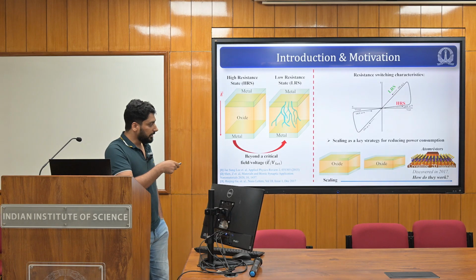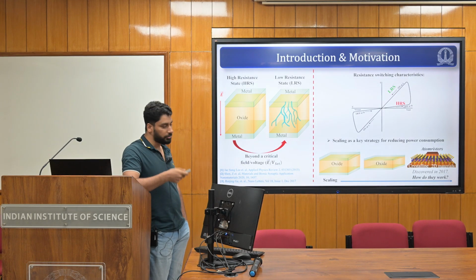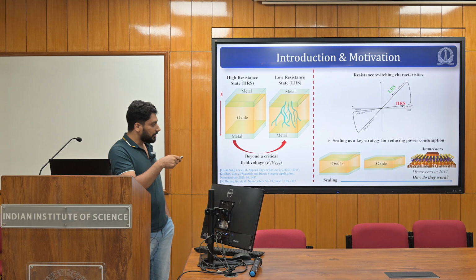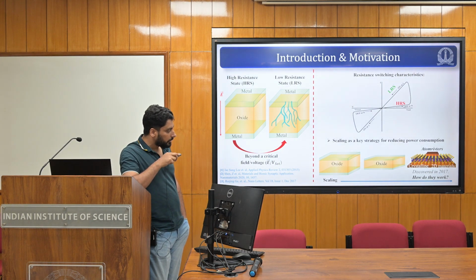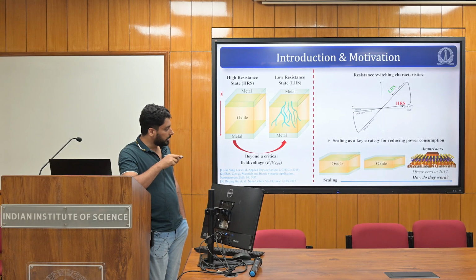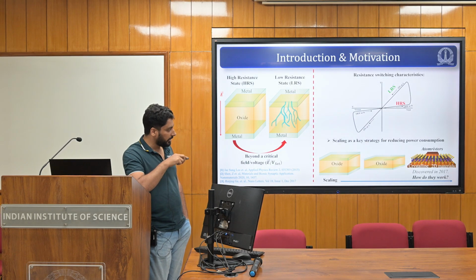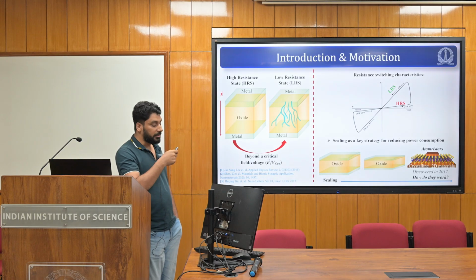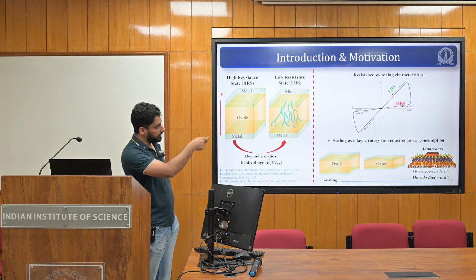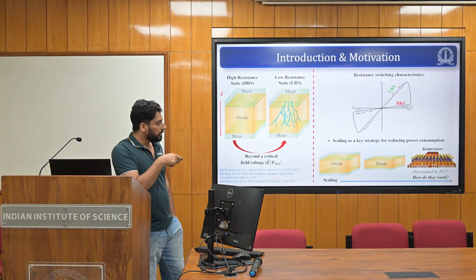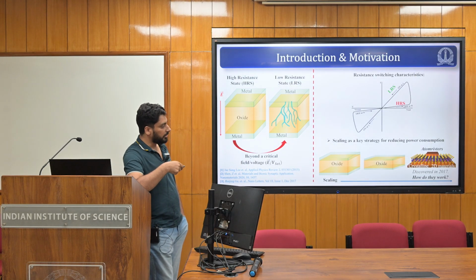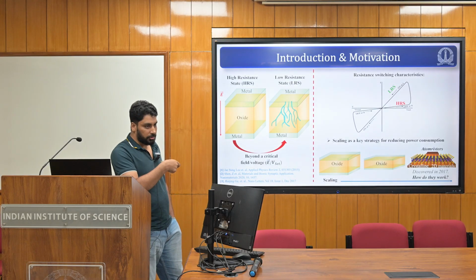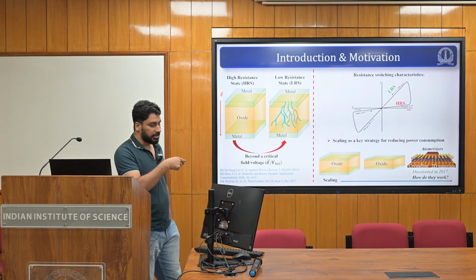Until recently, in 2017, although it has been almost a decade now, people discovered that if you put a monolayer of 2D material, which is just 3 atoms thick, in between these metals, they also have a resistive behavior like this. The hysteresis will be seen there. But up till now, the physics of these devices is not well understood, so ongoing studies are going on.